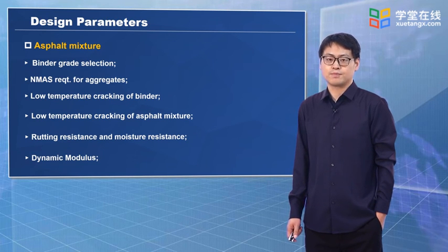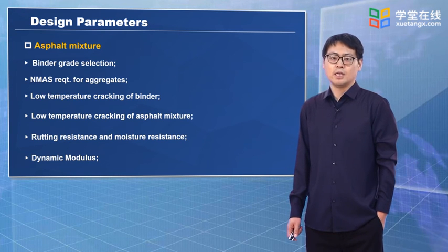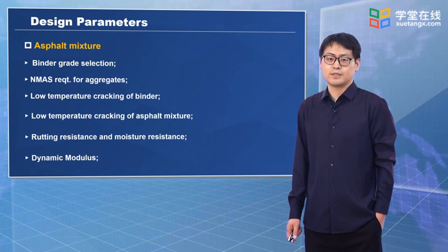For asphalt surface layer, dynamic modulus should be tested at 20 degrees Celsius and 10 Hz, and 20 degrees Celsius and 5 Hz for asphalt base layer. It should be noted here, sine wave type load was applied, as compared with the half-sine load applied in the resilient modulus test.